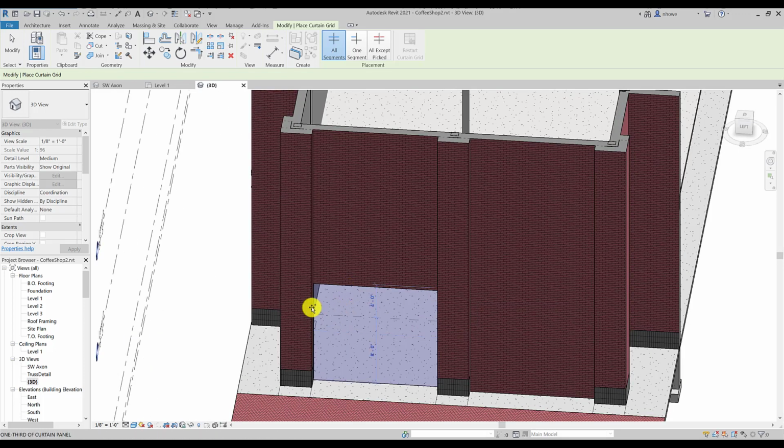What you couldn't see in the image was that there was a horizontal mullion at the 3 foot area, so we're just going to make one there. You can see that it's highlighting, you can see like a dashed line come into play. That is telling you that you're doing a vertical, so wherever the dash is, that's where it's going to put it.